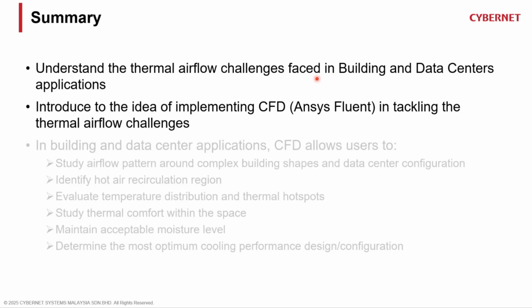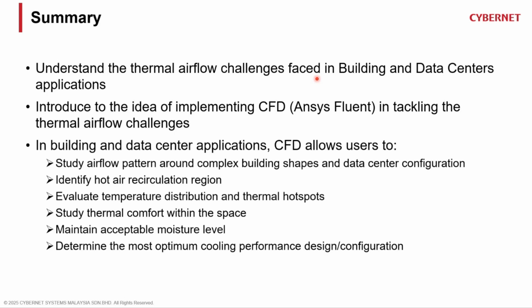In building and data center applications, in a nutshell, CFD allows you, first and foremost, to study the airflow pattern around complex building shapes or data center configurations. By doing this, you get to identify hot air recirculation regions, or even evaluate the temperature distribution. Is it too hot, or is it within the safety range? Or if there's any hot spot there.